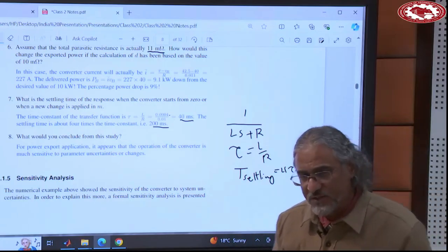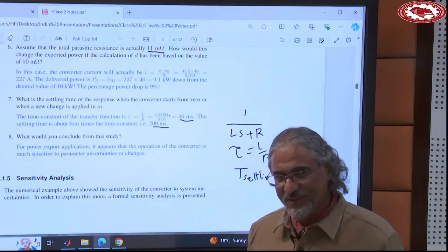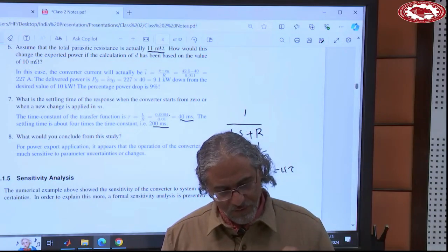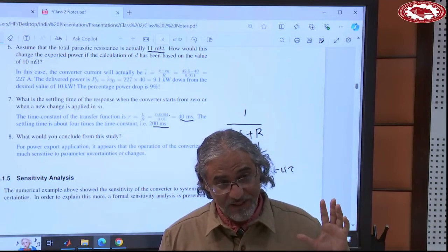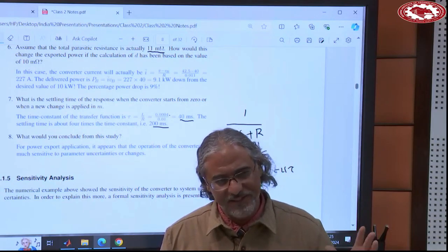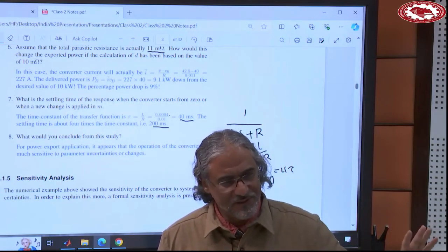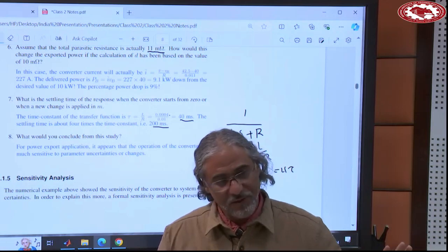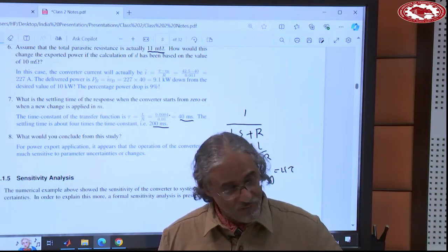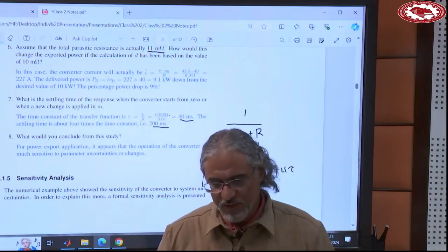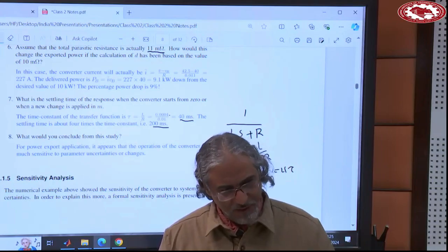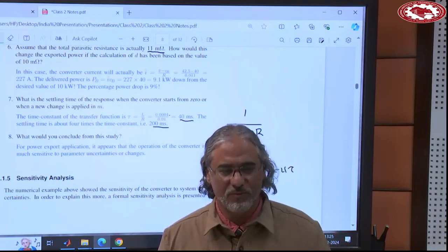If there is a scenario, and at some point we will go into that, that you release the first converter from controlling the PV voltage, how? Again, you will see there are situations where you can release it and say, don't worry about that voltage. Can you control this one on the other side? And then you may ask, who is going to control the other voltage? You will see that if the whole situation is put together in a proper way, the voltage at the PV terminal will automatically be controlled.